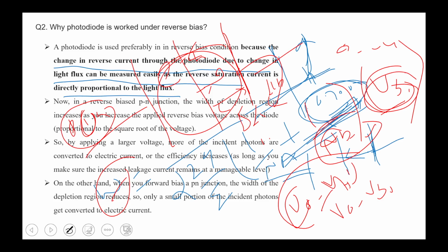Some photodiodes work on the photoconductive effect, others on the photovoltaic effect. So there are different mechanisms of photodetector depending on the material of the device and what kind of contact you use, like a Schottky contact or ohmic contact. It is a metal semiconductor metal type of photodetector. It depends on your design, material and type of photodetector, and you have to decide forward bias or reverse bias. But a standard photodetector works in reverse bias only.